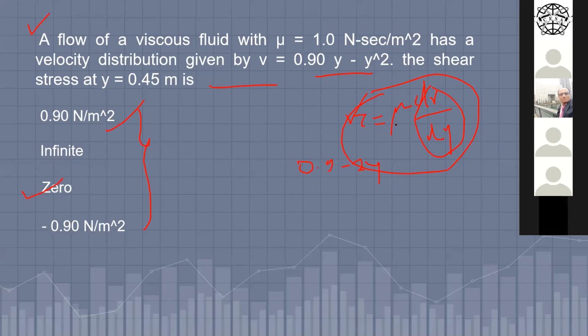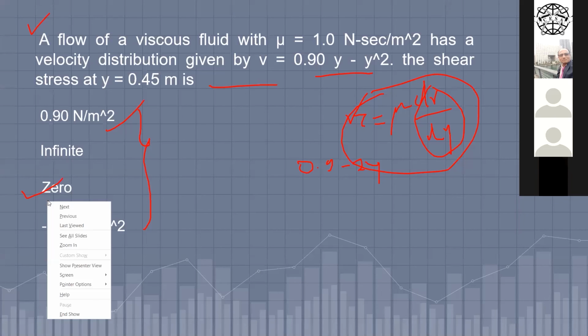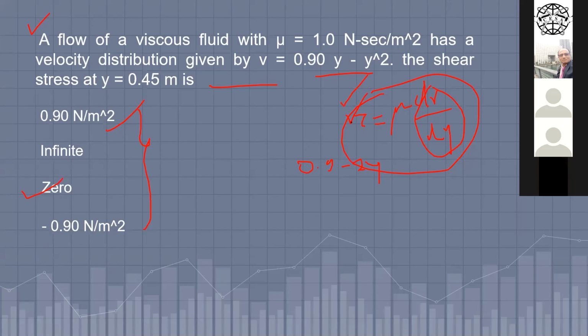Here Newton's equation of viscosity can be applied whenever there is one plate stationary and the other plate moving. So either a piston, one cylinder moving inside another cylinder, or a ram moving in a cylinder. Or you have an inclined plane, and on that you put oil and leave a block. The block is moving, whereas the inclined plane is stationary. Like this, it finds various applications in real practice, which will be discussed in our classes.